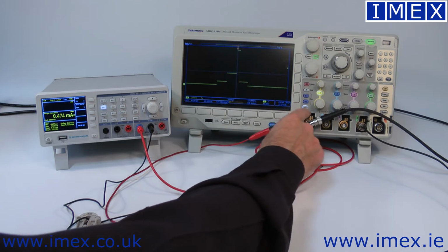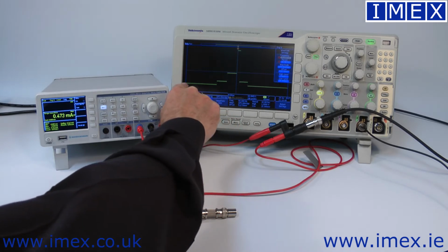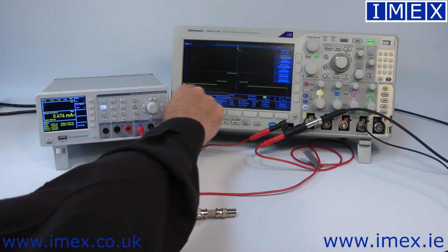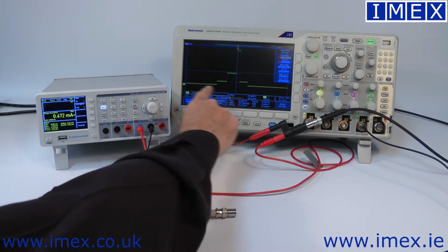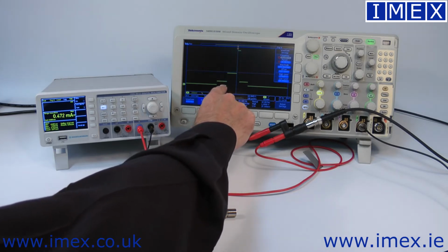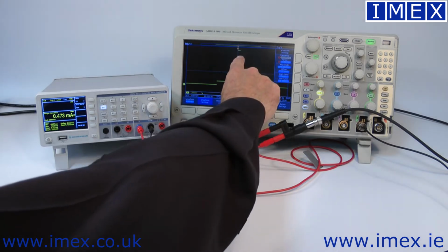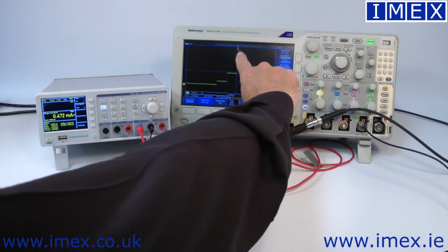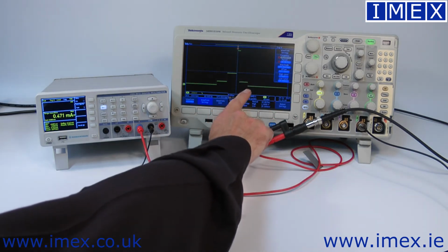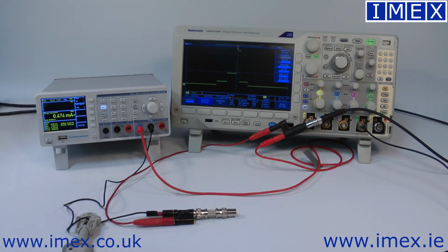Let me show you the waveform settings. What I've done, I've put a 25 millivolt low level, so corresponding to our sleep current here, I have 25 millivolts. Then stepping up, perhaps as the processor woke up, started processing, maybe turned on its sensors, gathered some data, switched through to transmit mode is our high peak, and then switching back down to a relatively low level as it tidies up and then goes back into sleep mode. So that would be kind of representative of a typical IoT device.